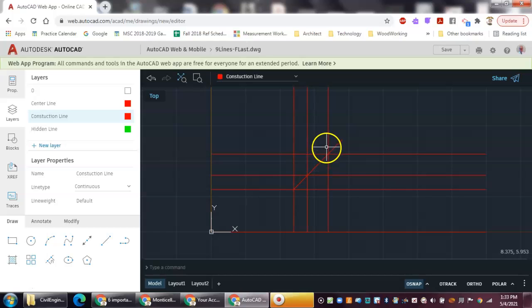The reason for manually keying and making sure that you put this at 45 degrees is because if you've messed up the placement of any of these lines, it's going to show that. Notice all of these should be the same size, and they should intersect, so you get a perfectly bisected square or these equal triangles as you go. If you don't have that, then that's a clue that tells you you haven't done something right.